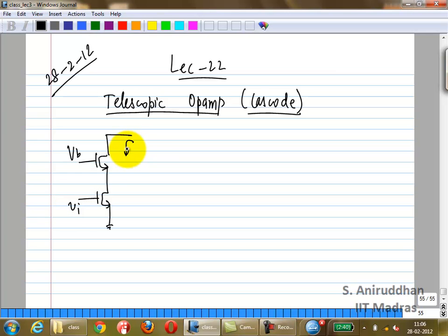Okay, so we know if I just take a cascode transistor, by now we know a lot of things. We know what is Rout. Let me call the transistors 1 and 2. So it's gm2 rds2 times rds1, and of course that is the approximate expression. The actual expression also has some other terms like rds2 and rds1, which we usually ignore because there's enough gain through the op-amp.